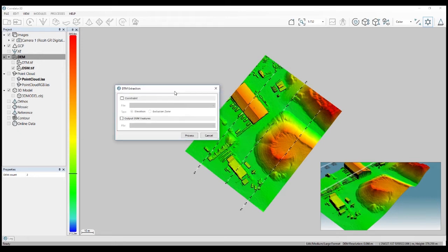I suggest that in some cases where you have already some bare earth topographic feature like this here, these stockpiles, a very steep feature, you can exclude those areas from the processing to avoid the software to filter or maybe even remove some of these topographic features that you would like to keep in the terrain model.